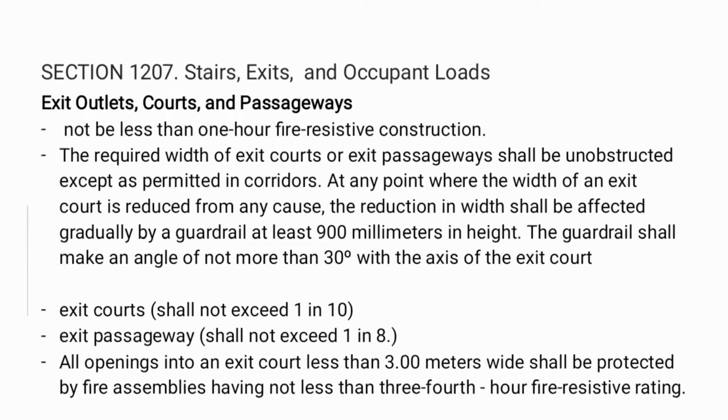And next is the exit outlets, courts, and passageways. So, the enclosure walls shall not be less than 2 R fire-resistive construction. Second, the required width of exit courts or exit passageways shall be unobstructed except as permitted in corridors. At any point where the width of an exit court is reduced from any cause, the reduction in width shall be effected gradually by a guard rail at least 900 millimeters in height, and the guard rail shall make an angle of not more than 30 degrees with the axis of the exit court.